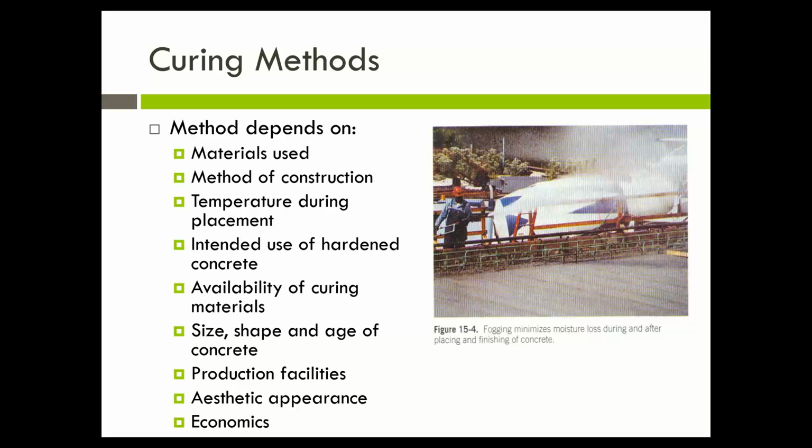If you go onto the App Store for Google or for Apple and search for hot weather concreting apps, you'll find that there are some that will estimate for you the rate of evaporation and tell you when you need to be fogging or not. For hardened concrete, so much of the curing depends on what materials we have available, what our method of construction is, what the ambient temperatures are, and what we really want the concrete to do when it's done curing.